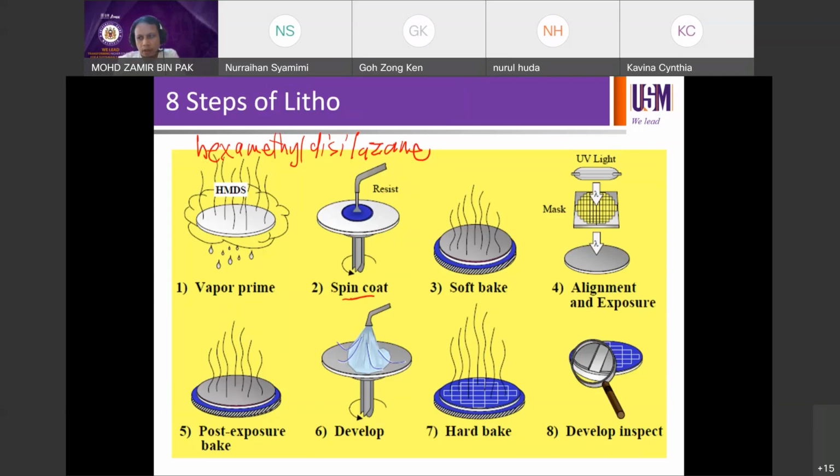Usually, this differs by fab, process and technology. When I handled this process last time, it was around 1 ml per dispense. So you're going to have a nozzle that can dispense 1 ml of photoresist on an 8-inch wafer that already has oxide. Then the wafer will be spun at high RPM, typically in the region of 3,000, 4,000 RPM for about 30 seconds to 1 minute, depending on the process.